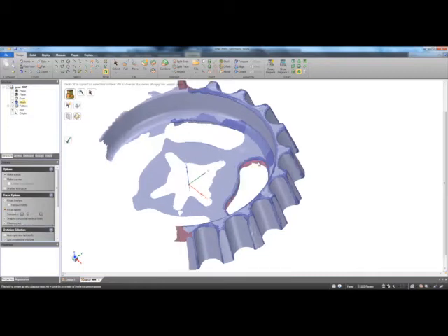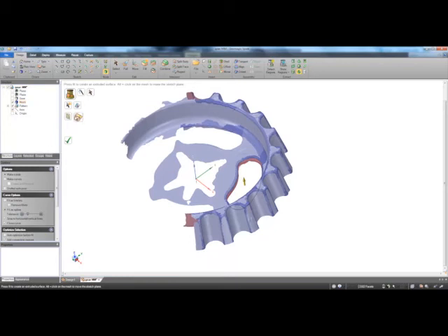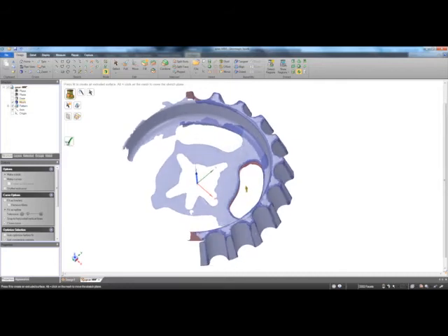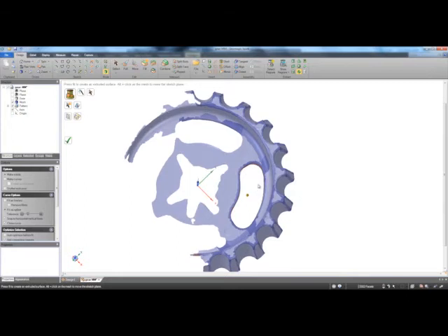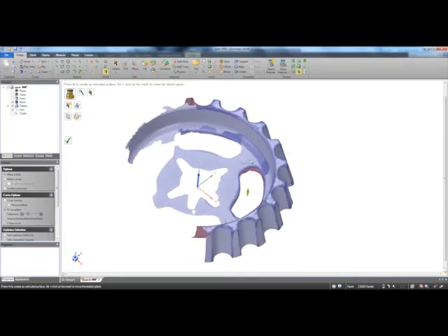I'm going to select this area, and then again I can constrain the orientation to the Z direction. If you wanted to fit it to a line arc, you just change it over here. And as well, you also have the ability to fit that extrusion and place that sketch on a sketch plane if the end user wants to do that. But for this demonstration, we're just going to leave it where it is. We're going to say make solid and go ahead and say complete.